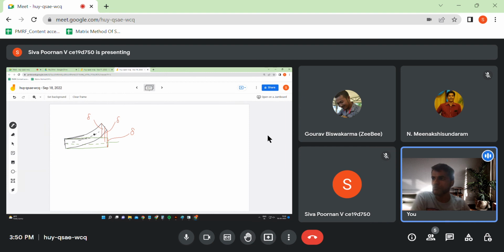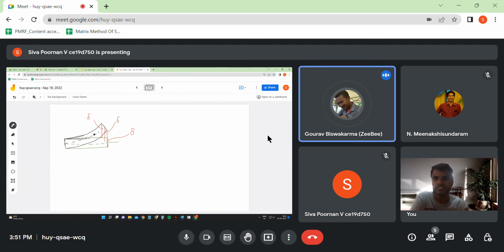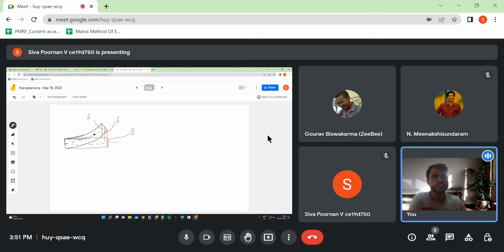Basically, from Euler-Bernoulli theory, what we say is that bending is entirely due to longitudinal strain. It's just a linear variation of axial strain. There is nothing else in it. No other strains. There are no shear strains. There is no thickness reduction. All those are ignored. That is why we can safely assume that the vertical deflections of all the fibers will be the same. Not just the middle fiber, top and bottom, but every fiber will be the same.